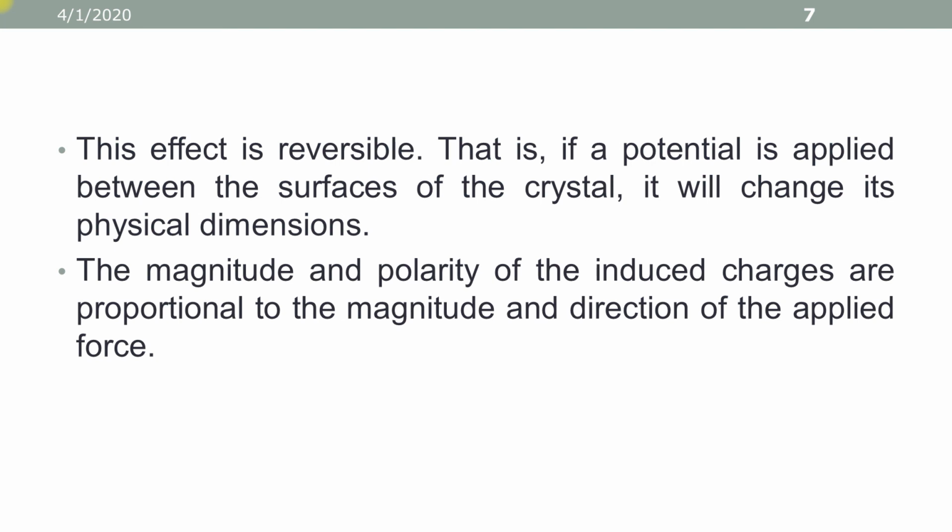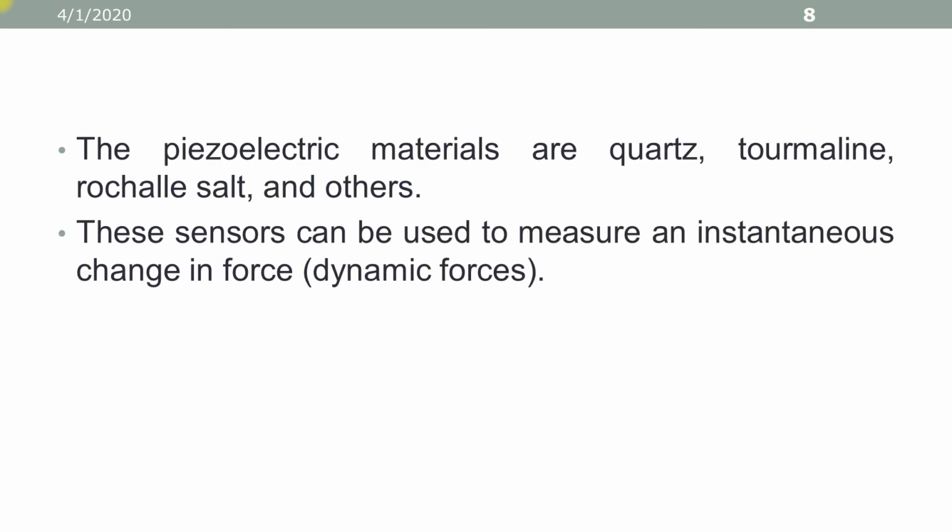The magnitude and polarity of the induced charges are proportional to the magnitude and direction of the applied force. From this property we can calculate force and pressure. The piezoelectric materials are quartz, tourmaline, Rochelle salt and others. This sensor can be used to measure the instantaneous change in force, that is dynamic force.